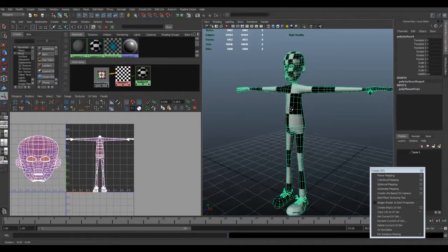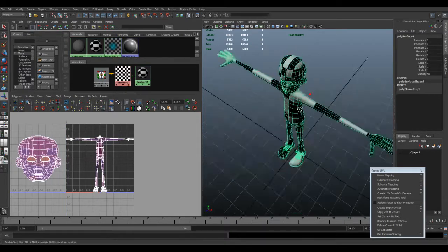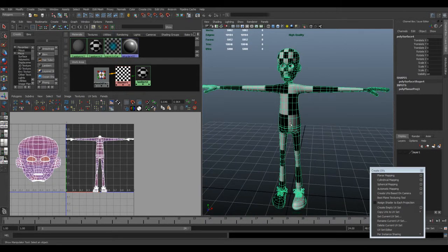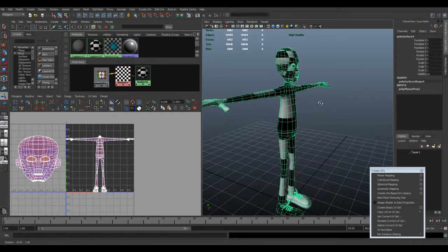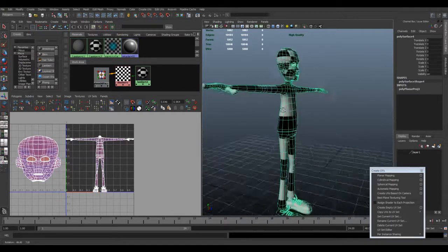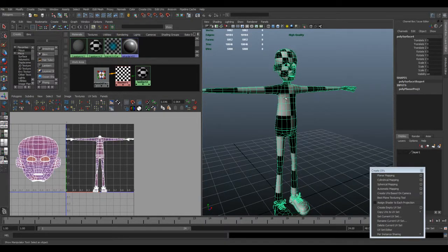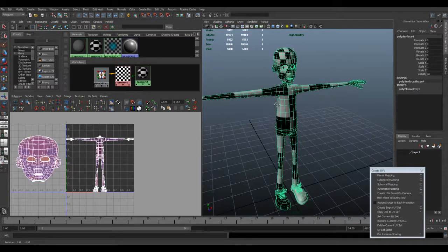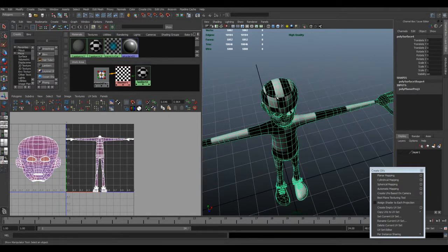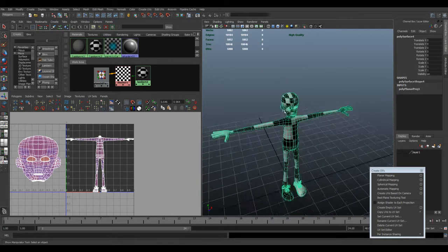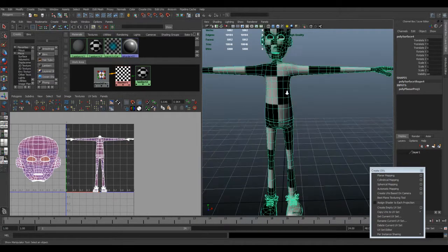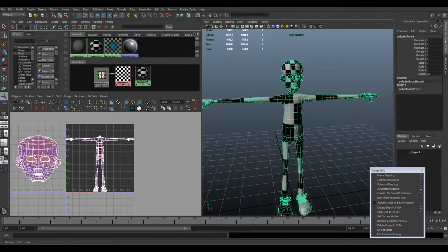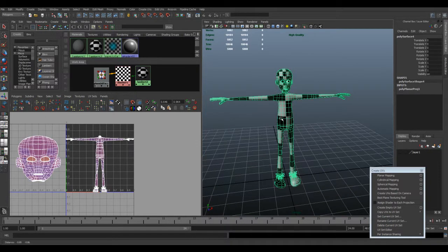Now, what we aim to do at the very early stages when we're texturing is spread our texture evenly across the whole character. Obviously, this square box here is the same size as this square white box here. The problem with that is we're stretching the same. If we put a texture onto this character, we're stretching that texture over this area, 1, 2, 3, 4 deep by 5 or 6 wide. We're stretching that texture over that big area, whereas up here you can see there's much more detail in the area. So what you're aiming for really is, in areas where you need detail, like the face, which is definitely a high detail area, but you want to try and get an even spread of these